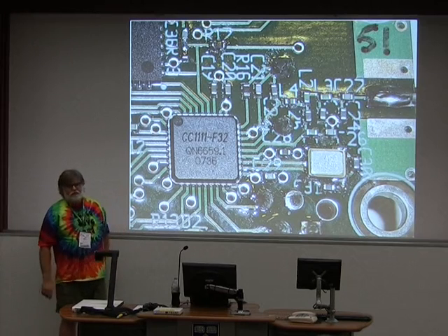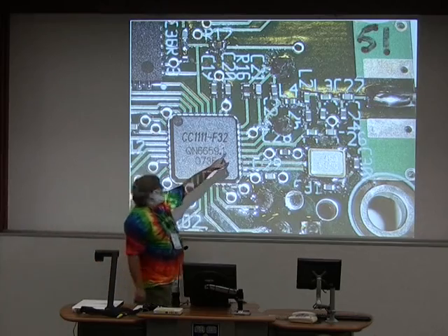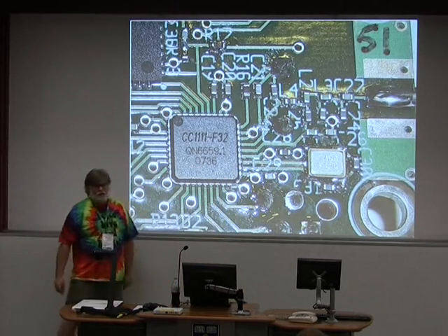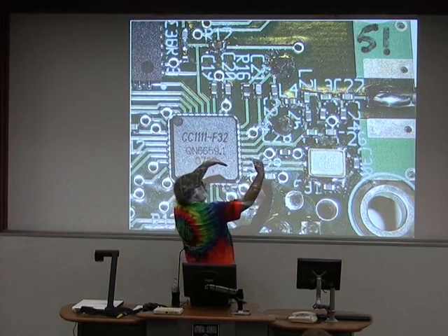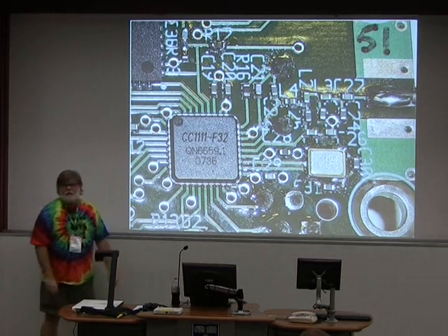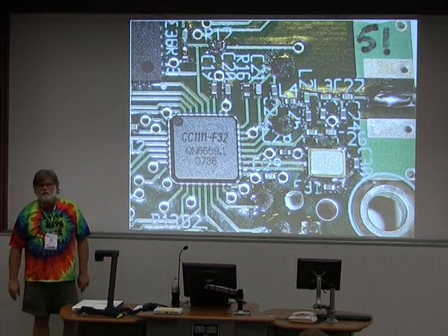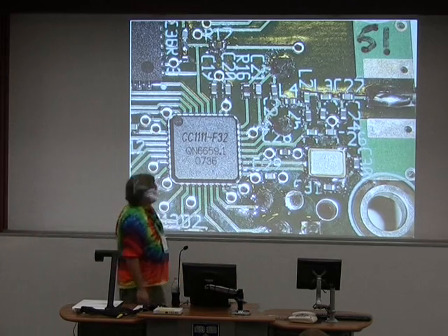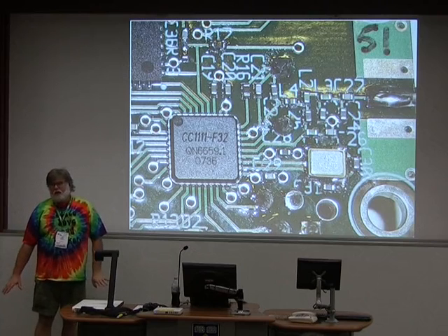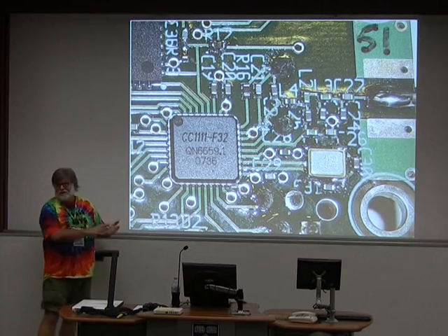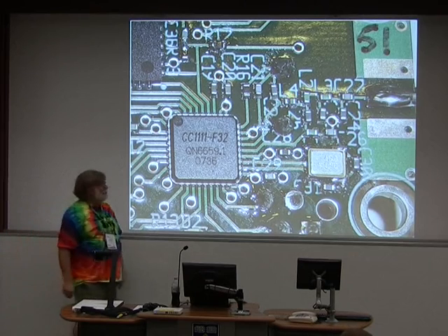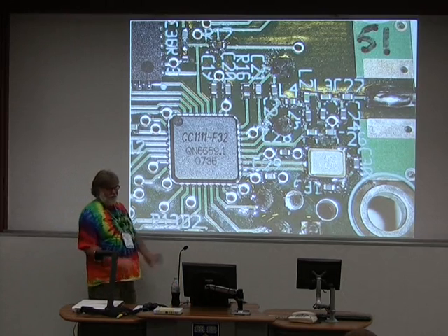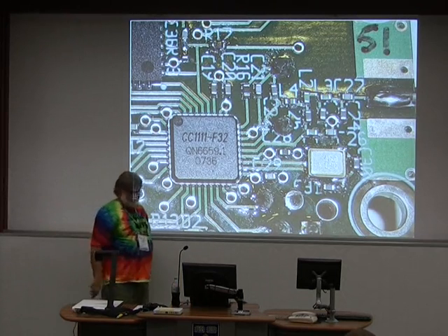It turns out that even in 0402 surface mount parts, this really still matters. And so you'll notice that the little parts that have a greenish tinge, like that one and that one and that one, are inductors. And you notice the orientation of the one in between. I've got two of them like this, and the one in between's like that. It turns out that that's good for 0.3 of a dB, something like that. Likewise, on this board there aren't many situations like that, but you have to not throw away everything you know about radio design just because you're doing cute little surface mount parts that are all gorgeous little rectangular solids. Those really are inductors, and they behave like inductors, and they have EM fields around them, and if you line a whole bunch of them up neatly on the board, they will all couple to each other and just work like crap.